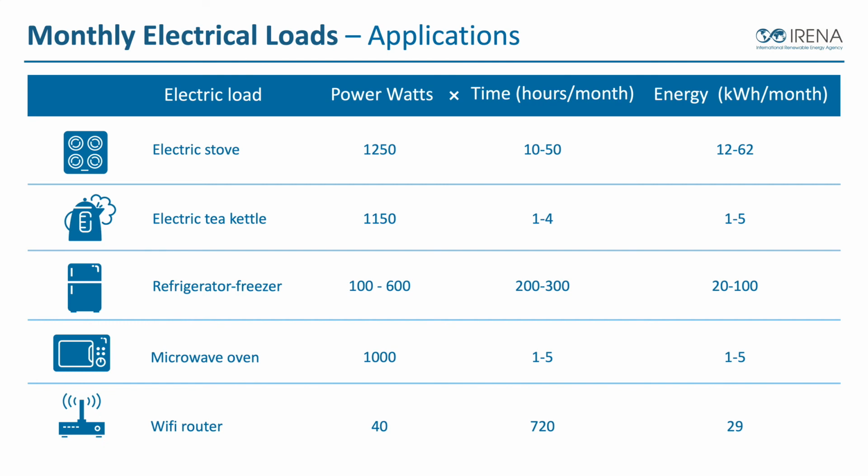Now, the other thing with refrigerators is they have what we call a cycle time. So they turn on, turn off, turn on, turn off. The compressor's run time is based on keeping the refrigerator at the set temperature. So some of the other variables here can also be, what is the air temperature outside of the refrigerator? If this sits in a very hot climate, it could run a lot longer to keep the internal temperature correct. If it's in a cooler space, then the compressor doesn't have to run very long in order to keep the internal temperature at our setting. And so refrigerators are hard to calculate their actual watts and energy consumption.